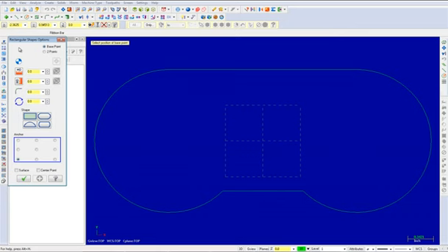Make the following changes. Enter a width of 0.275 and a height of 0.75. Also, change the anchor position to center. Now select the following circle center point as shown. Once complete, select the Apply button to stay within the command.